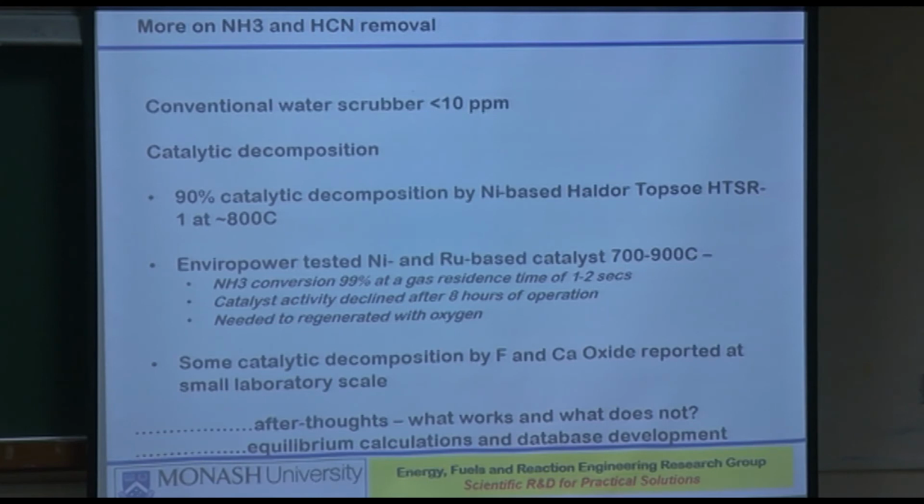So the catalyst activity declined on this particular system after 8 hours of operation, and it needed to be regenerated through oxygen. And that brings it squarely into the area of regeneration. Almost all the regeneration reactions are exothermic, so that's one advantage.